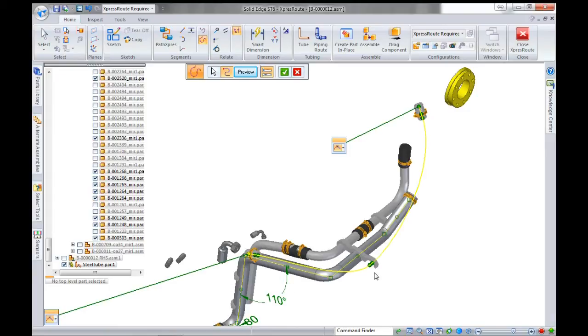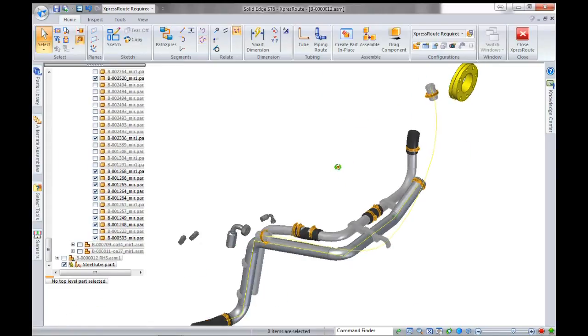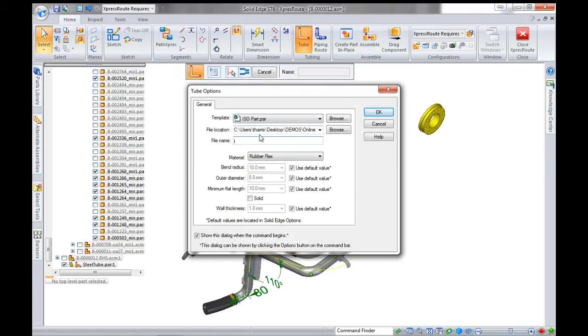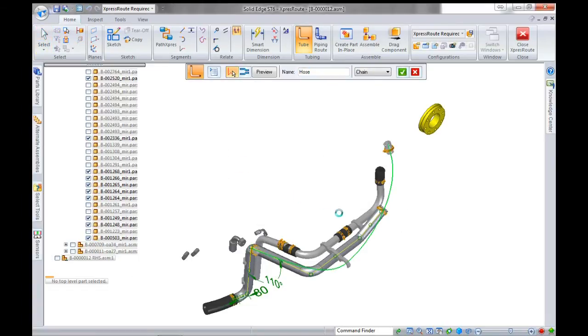If you only want to use a couple of specifications, then you might tend to use the tangencies and the handles to control how long the tangent follows. Because I deleted the previous hose, I'm just going to recreate this hose with new parameters, and I can just overwrite the existing properties or the existing hose.